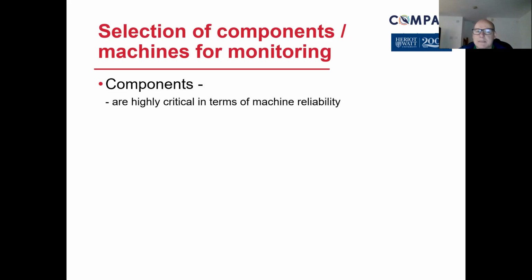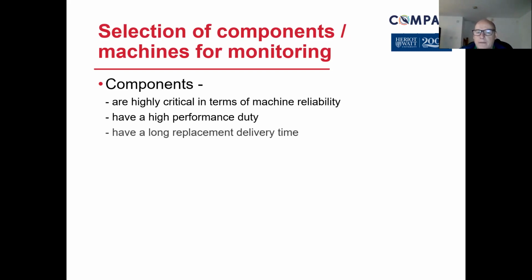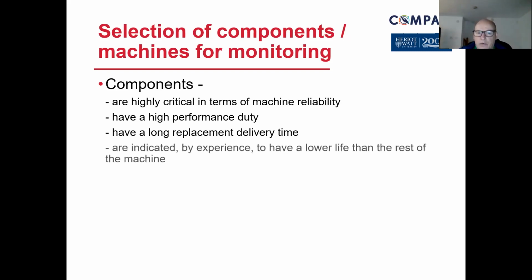Again, going back to aspects of reliability linked to maintenance. The highly critical pieces of equipment need to remain reliable, and therefore, if they're not, more maintenance is required, more inspection is required. So look at those and identify where the life cycle could impact on this. They need to be high performers, and may have a long replacement delivery time. If they do have a long replacement delivery time, then you need spares so that you can immediately replace rather than put others at risk, or take shortcuts, or put something else in place that's perhaps inadequate. Again, the higher the level of risk, the more you have to rely on these things, because it's just not worth taking the risk.